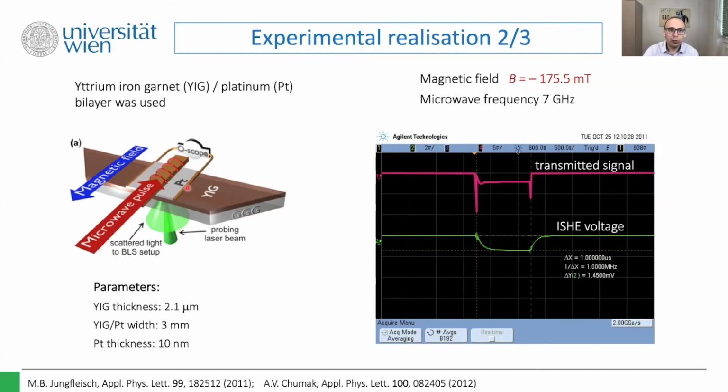And if you look now at the voltage measured here, this green channel, you see that we have voltage. So it takes some hundreds of nanoseconds, but this is related to the dynamics of spin waves. So you need to excite magnetization precession for some time. Then after you switch off the pulse, it still will take some time to dissipate, like we already know. But the main message is that we see voltage. And this voltage is 1.5 millivolt without any amplifier. That means that this is a very robust, powerful effect.